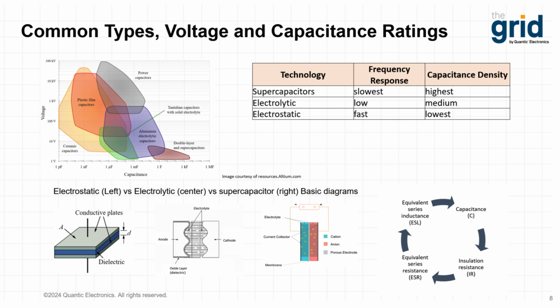Electrostatics are used heavily in circuits for snubbing due to their ability to handle AC currents, higher isolation voltages, and faster frequency responses. Electrolytics have very high capacitance density and can be used for applications like rectified voltage smoothing, bulk energy storage, or bulk capacitance in a power supply input.